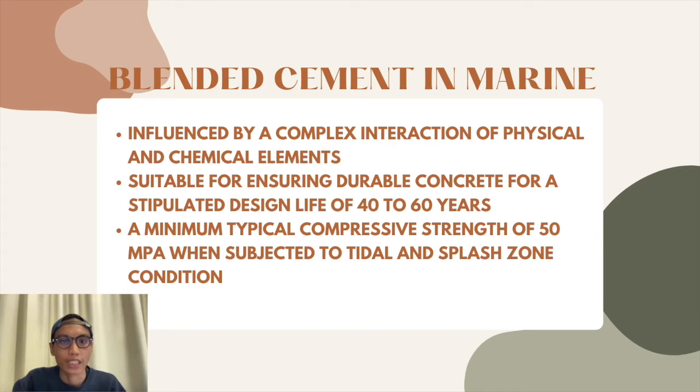Water absorptivity has been specified as a criterion for concrete in marine application in conjunction with prescriptive requirements for minimum binder content, maximum water binder ratio, and binder type by certain public authorities in Australia who require longer structural design life of over 100 years.